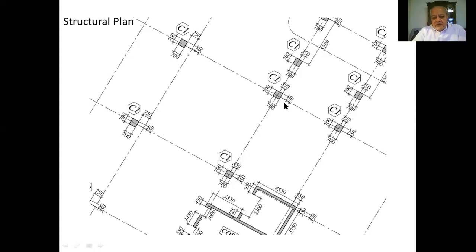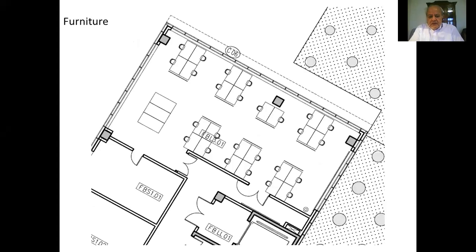And when they work with this, they might not end up with the same preliminary dimensions that you have here. They might need larger or smaller columns. Then we go into a phase of discussion and reviews and try to bring our two views together, to have the best structural elements and sizes in our design.